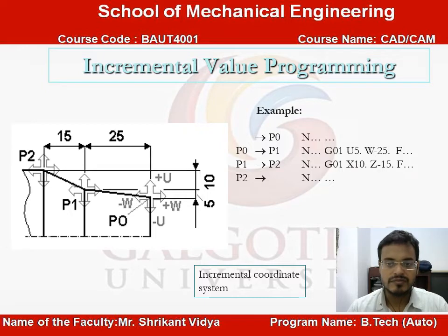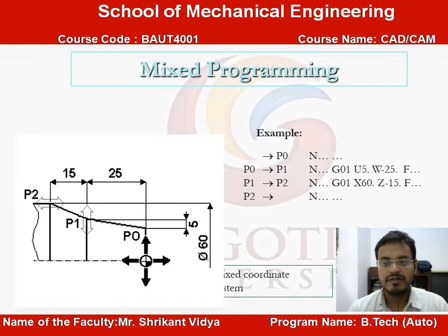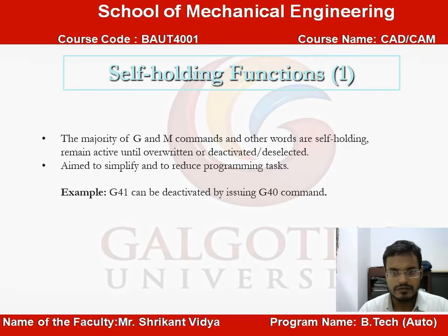Now the incremental system: the origin changes from step to step. For the next point, the previous point becomes the origin. So you can see P0 to P1, then P1 to P2. The coordinate system varies from point to point. Mixed programming means somewhere incremental is used and somewhere the absolute system. According to the ease of programming and the requirement of the program, for complex programming we go for mixed dimension, a mixed coordinate system.